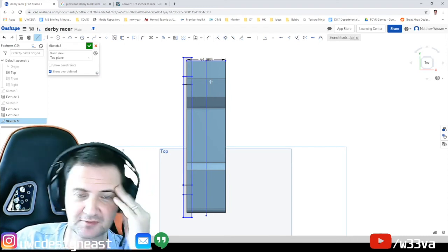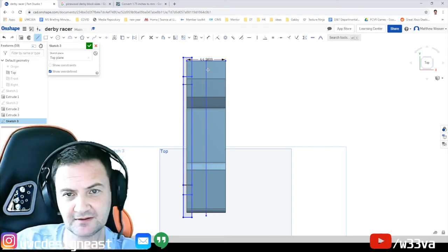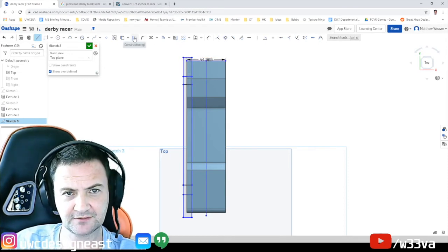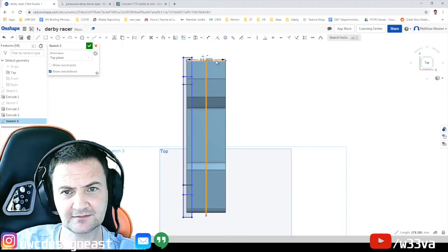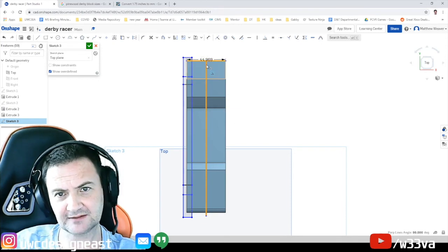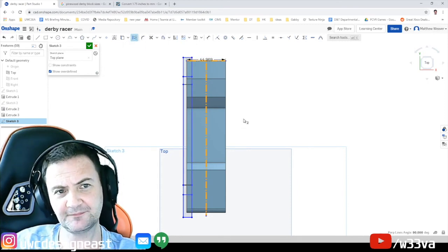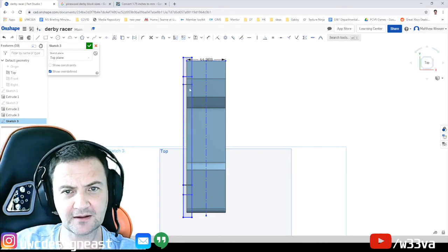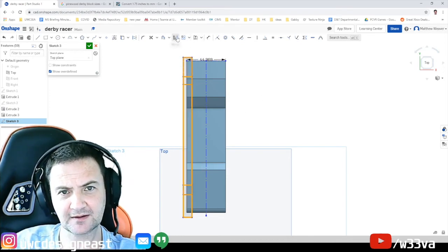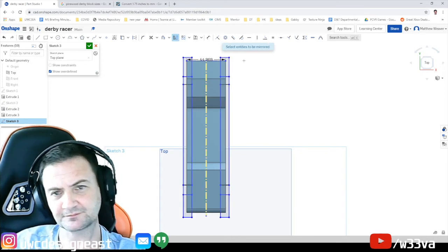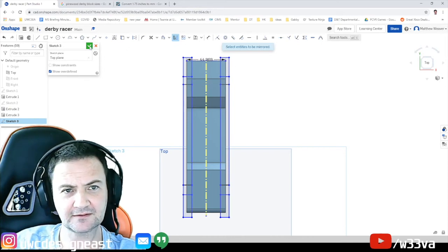So, do you remember we were talking about construction lines? I'm going to turn these lines into construction lines, because I'm not really bothered about them. I don't want to draw them. So there's a little construction line there. If I click that one off, select that, shift and that. So there's that T that I just drew, the line there with the mirror line. Then I can actually turn that into a construction line. Click off it. Then I'm going to highlight those. Click mirror. Select the mirror line, which is that one. And it should bring it straight over. Okay. And tick when you're happy.